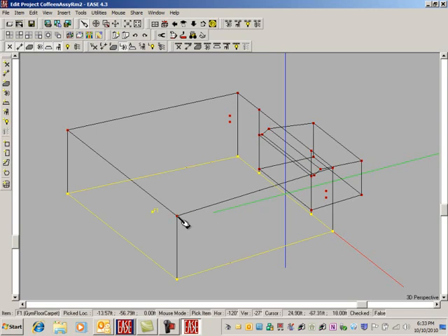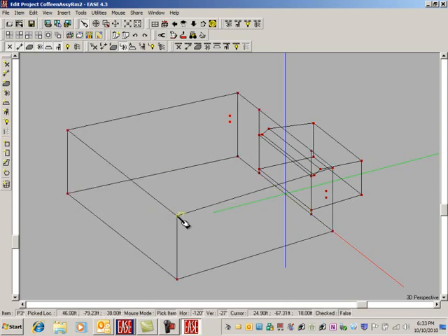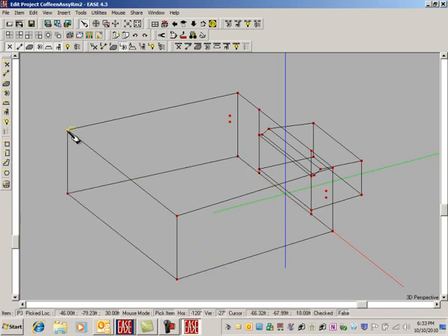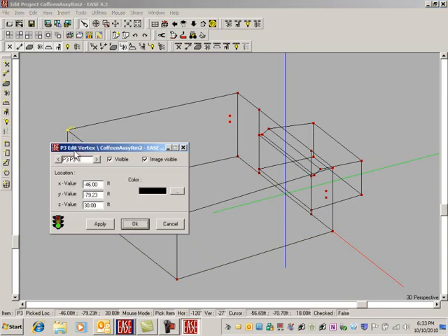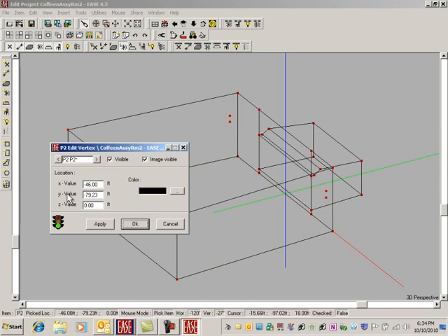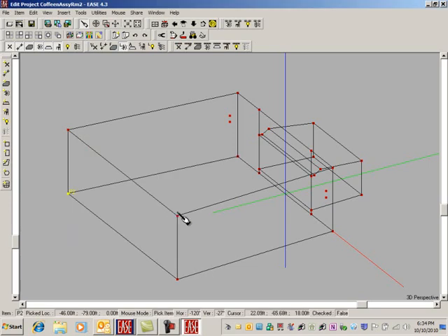Now, this face, it has two sides. I'm going to make it a two-fold face because it has a front side and a back side. I'm going to set the material as glass heavy on the face side and also the rear side. That makes the model look better when I render it. And I'm going to coat it on this face right here. So I have to know the number of that face. Well, I can go over here and select it like this. Oh, it's F3.